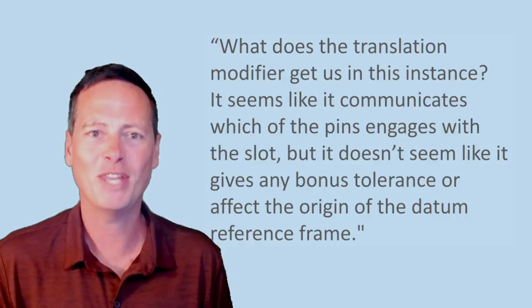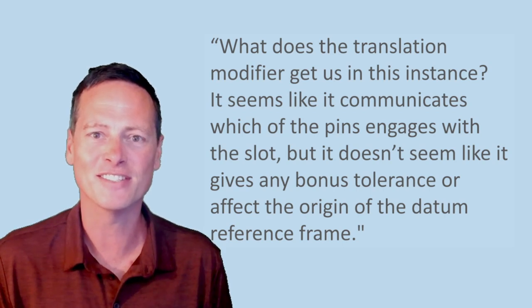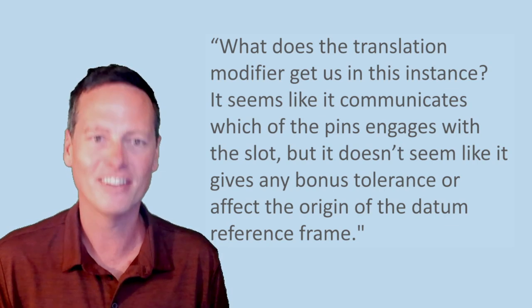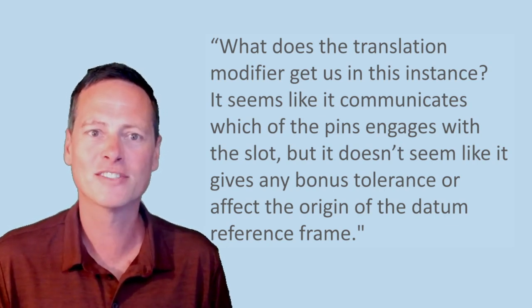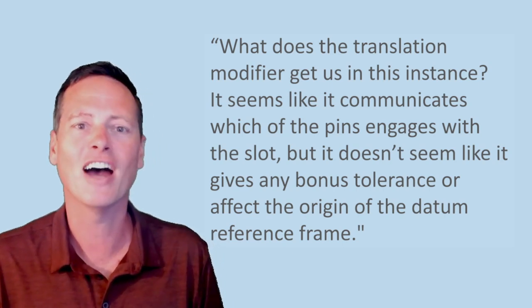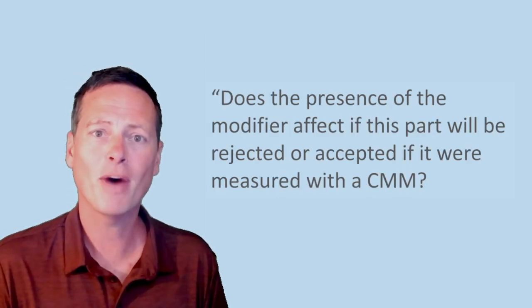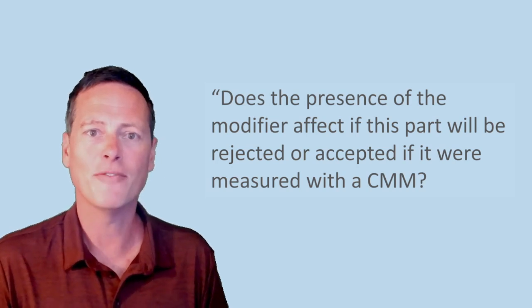Well, for now, let's bring this around full circle to where we started. Just to repeat from the comment, what does the translation modifier get us in this instance? It seems like it communicates which of the pins engages with the slot. Yes. But it doesn't seem like it gives any bonus tolerance or affect the origin of the datum reference frame. Yeah, I would think not. It's not really about bonus tolerance.